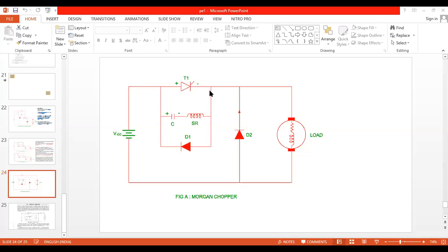Current enters the cathode terminal of the SCR, and from the cathode to C minus. It is the same circuit; the only difference is that there we used an additional SCR, here we use the saturated reactor. So case 5: the capacitor discharges from C plus to SR, to the cathode of SCR1, then the anode, and then to C minus.